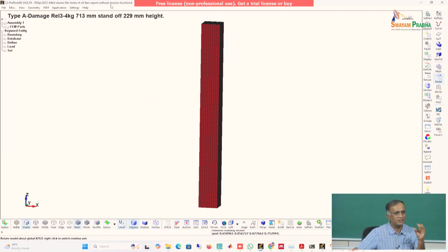So in a finer mesh, maybe erosions, you're not affecting it so much. So you have to keep track of what is known as inertial forces. So you have to track your actual forces, inertial forces, damping forces, and any other forces, thermal forces if they are there, or the energies, and see what percentage of each they are. And if your inertial forces percentage is low, then you can say, okay, erosion has not mattered.